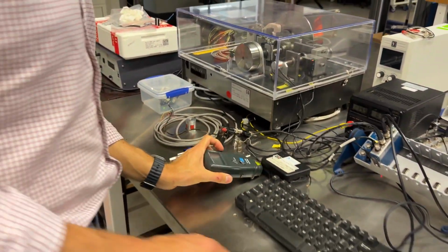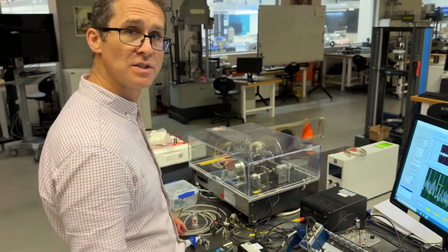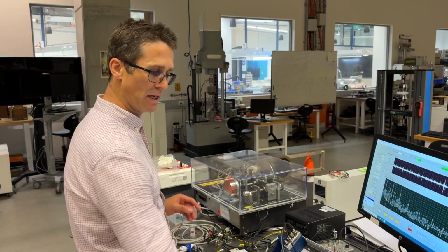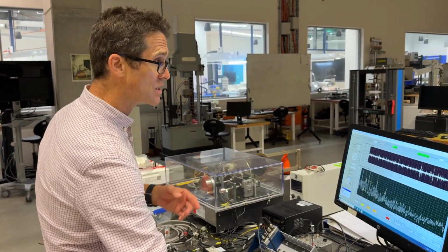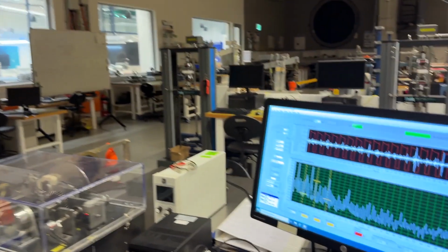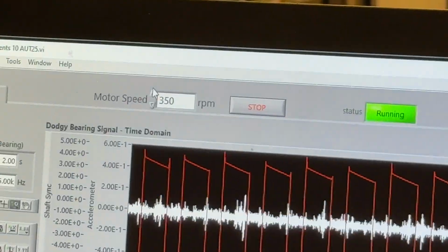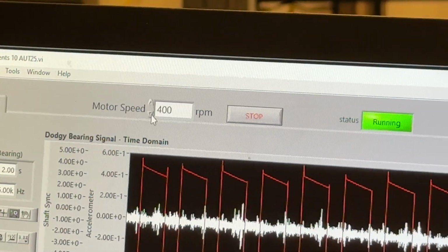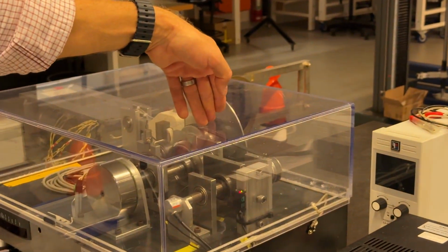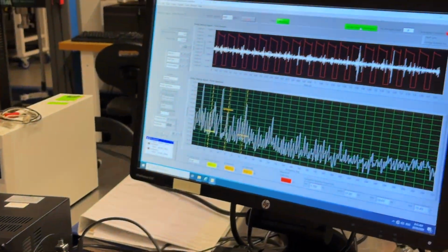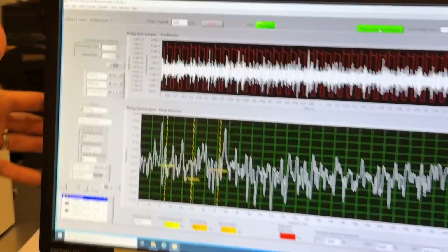That's a handheld tachometer. I've shown some other types of instrumentation for rotating machinery measurements, particularly for shaft speed measurements, in a previous video. In this video, we'll now increase the speed up to 400 RPM, which is going to be 1160 RPM on the shaft with the faulty bearing in it. I'll restart the spectral averaging on the software, and I'll explain what's happening in the software here.